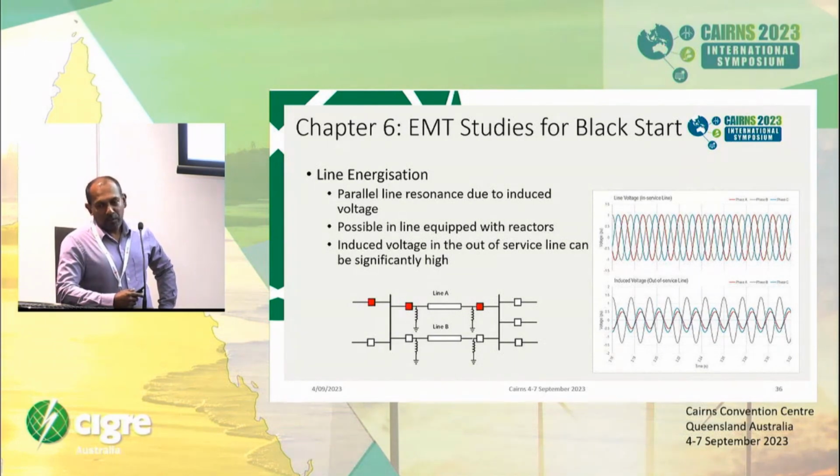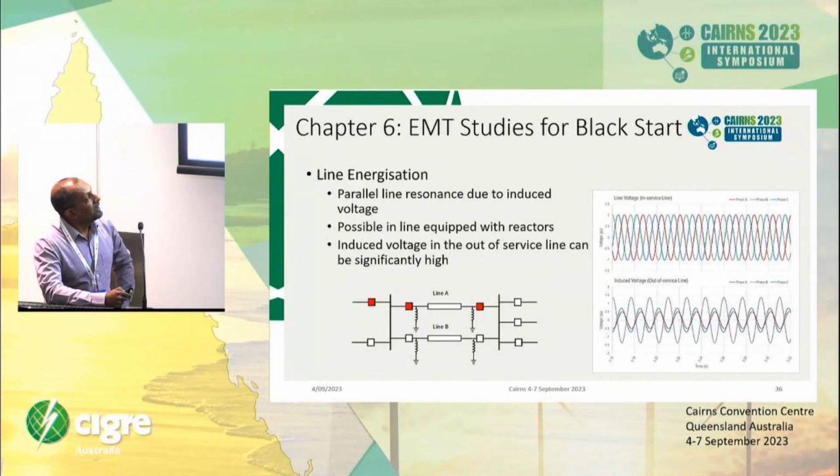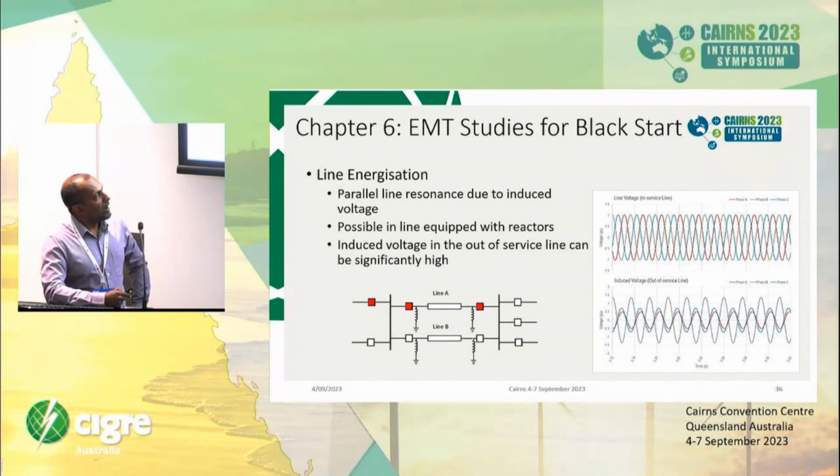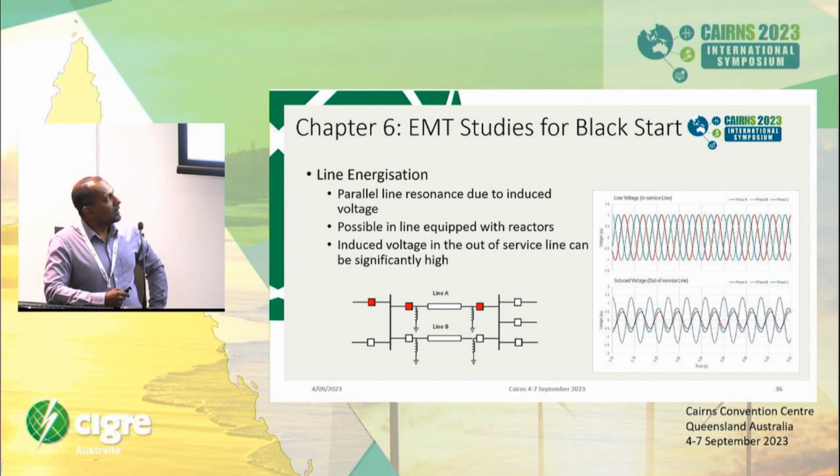Another phenomenon is induced voltage in parallel lines. Some people call it parallel line resonance. This could be the case when you have a long line equipped with line reactors. When you have two circuits together, there can be some induced voltage on the de-energized line due to the coupling effect with the already energized first line.